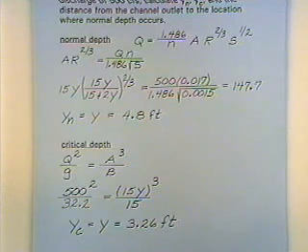So what does that tell us as far as the flow conditions to anticipate? We've got a normal depth of 4.8 feet. So if you get far enough away from the river, up the creek, up the concrete channel, so there's no effects, the depth's going to be 4.8 feet. But it's flowing into the river, so the depth's going to be 10 feet in the river. And so you're going from 4.8 feet to 10 feet.